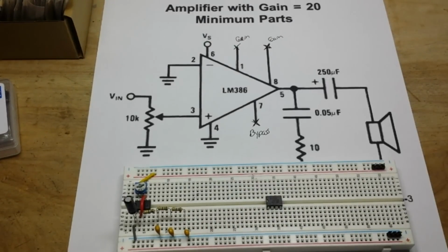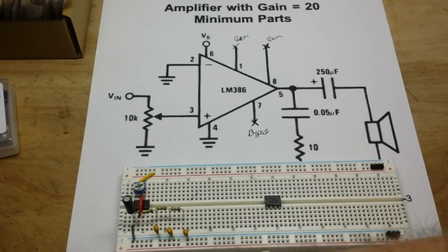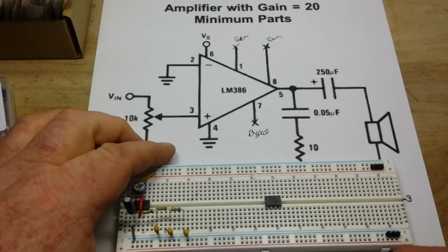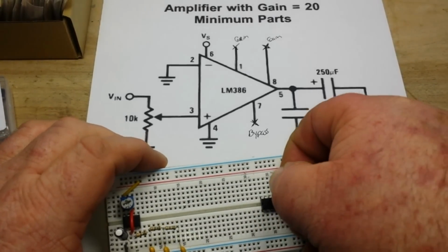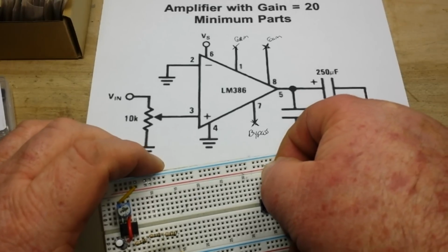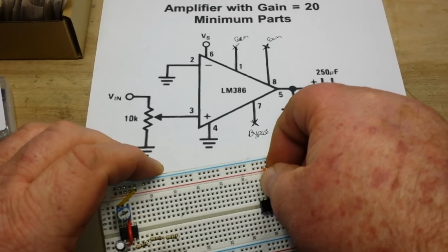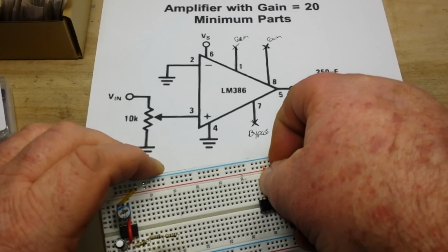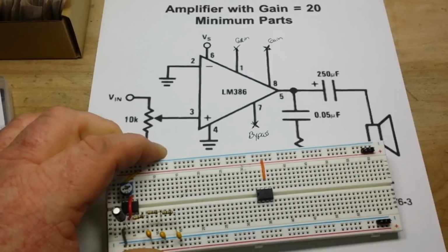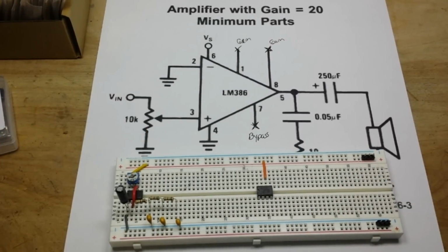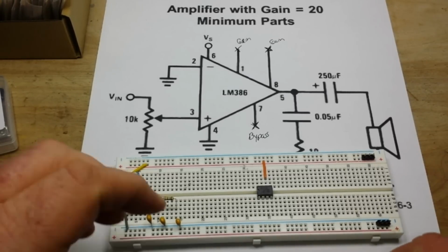We got some nice breadboard jumpers. The reds are too long, so we'll go with an orange. And that's pin 6. 1, 2, 3, 4, 5. This is pin 6 right here. So pin 6 goes to power. Nice. Pin 4 is our ground. We use gray for ground.